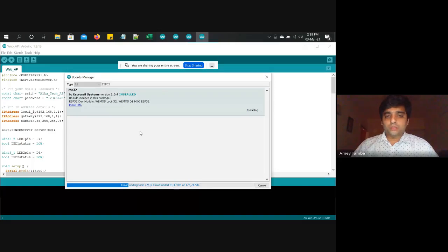If you are not updating the code and your base version, it will cause some problems, like your sensor is not properly calibrating, or your sensor is not taking data, or your sensor is taking data but the board is not displaying it, or the board is not properly initiating the sensors. It is not giving proper power, because everything is based on the drivers that the board has.